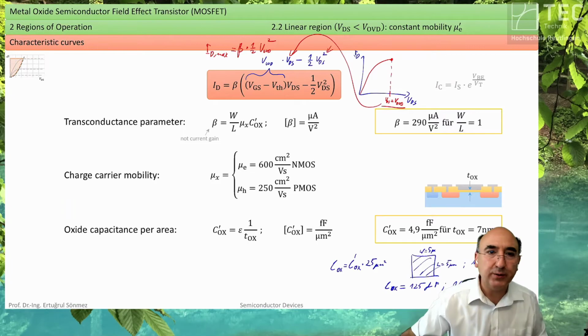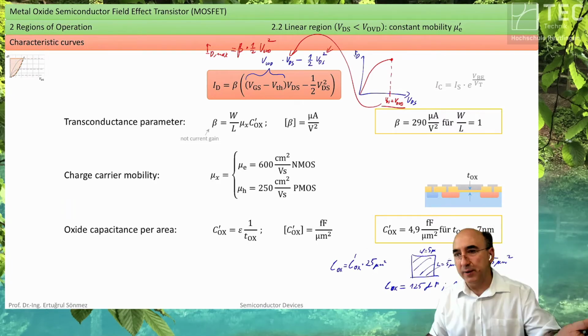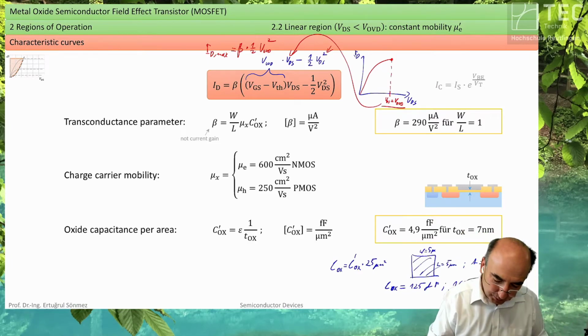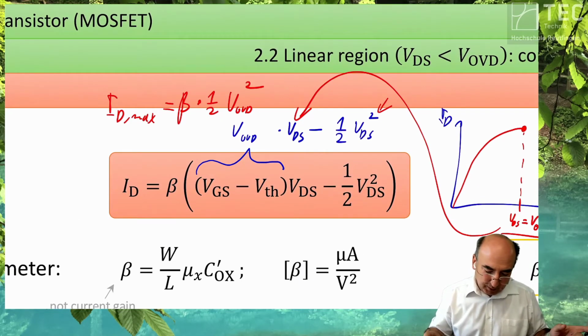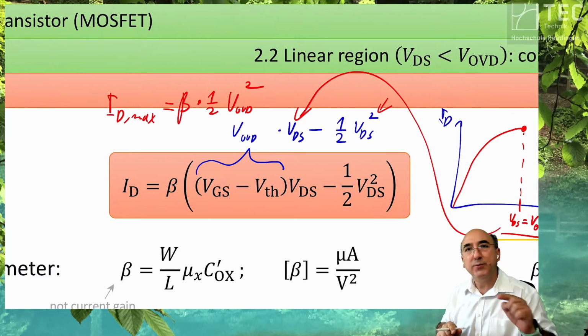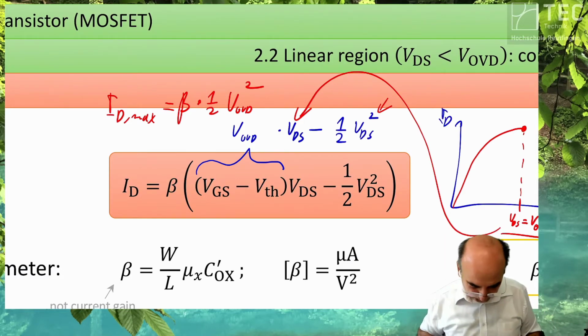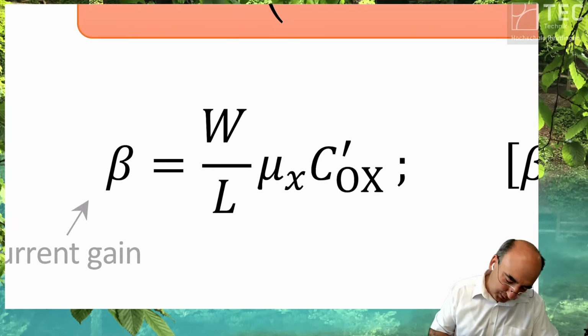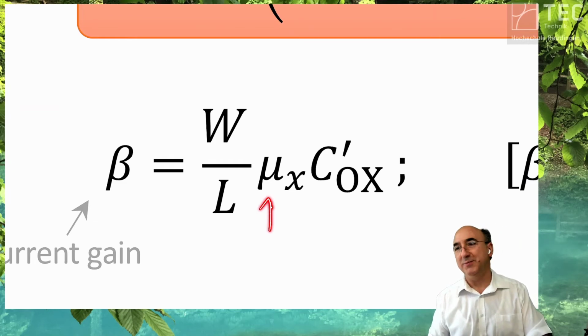Okay, so that's the point where we are to understand the MOSFET. So putting all this information vice versa towards questions, I can ask you how you can increase the current of the transistor if you are a technician. You can say, I try to increase the mobility.